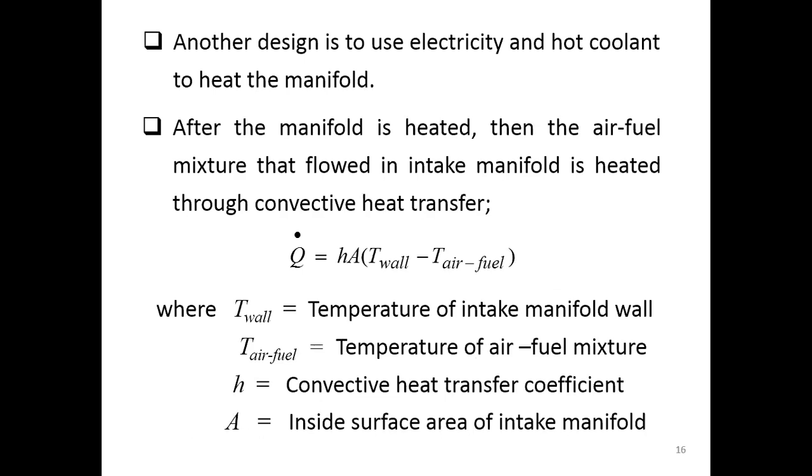Another design is to heat the manifold directly, not only depending on the convective heat transfer mode. This way, they heat the intake manifold directly using electricity or hot coolants. After the manifold is heated, the air fuel mixture that flows into the intake manifold is heated as well through convective heat transfer,